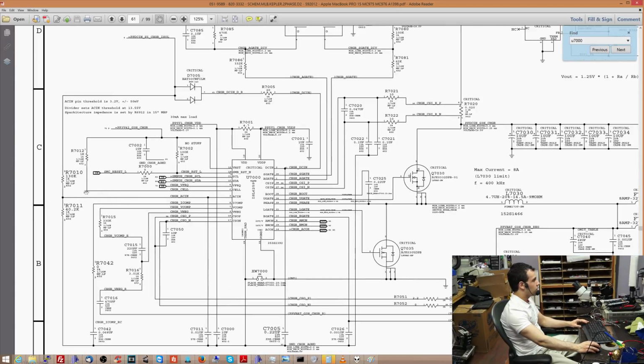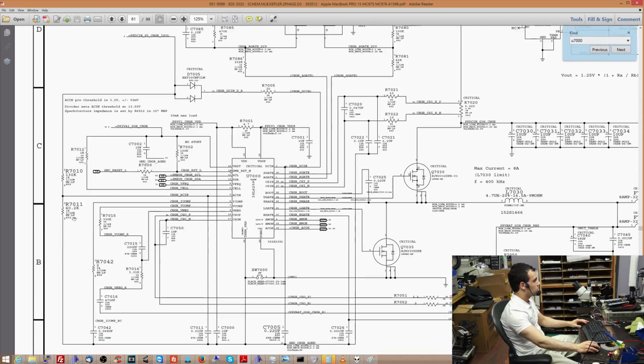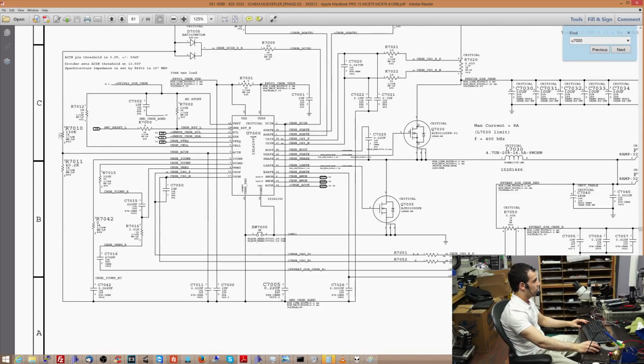let's see, over here you have charger voltage. So this is charger voltage going through these two resistors. One resistor is going to ground, the other resistor is going to ACN over here. That's called a voltage divider. I'm going to explain what a voltage divider is in a new video, so don't worry if you don't know what it is here. The whole point here is, you see how this resistor is 40 kilo ohms to ground? What if this resistor shorts, and now instead of being 40 kilo ohms, it's 0 ohms? What it would do is send the entirety of this to ground.